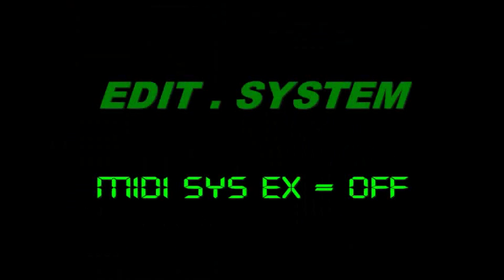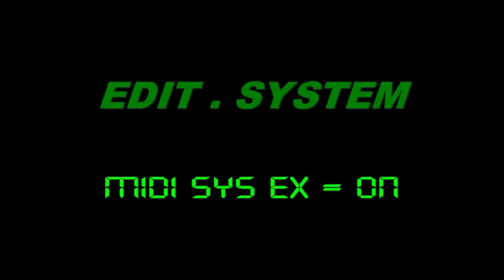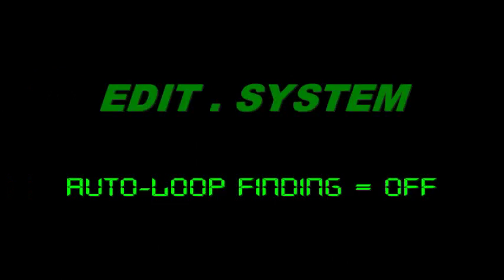To begin with, first set the EPS to do the MIDI system exclusive thing, so press Edit System, then scroll across for the MIDI sysx and set that to on. I found in MIDI transfers it's best to turn the auto loop finding feature off, so while you're there scroll across for auto loop finding and set that to off.